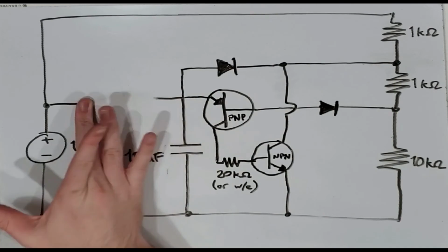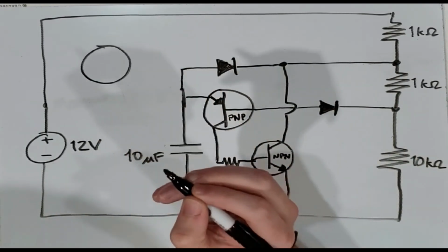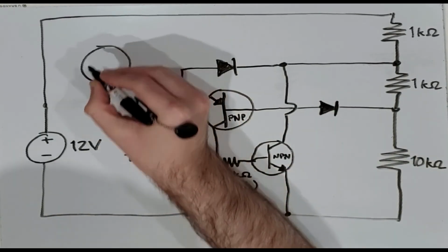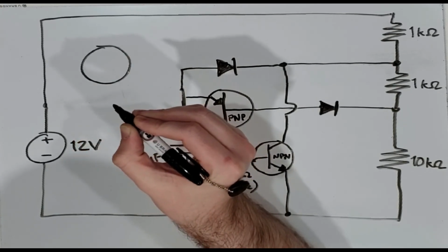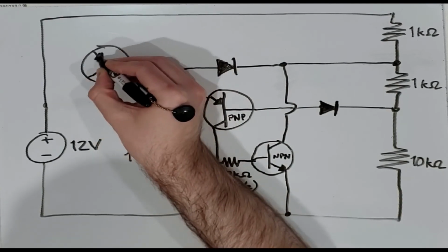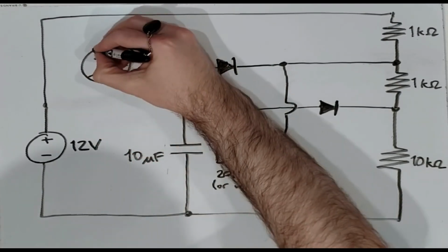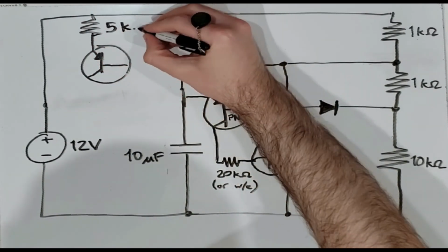One final easy improvement to this circuit is to replace the resistor with a constant current source, so that when we charge the capacitor, we do so at a constant voltage increase instead of an exponentially decaying one. Add a PNP transistor and connect the base of it to a voltage divider, which conveniently we already have one that we can use.